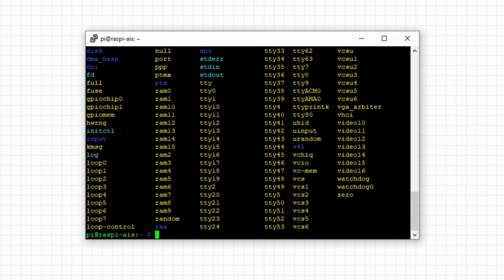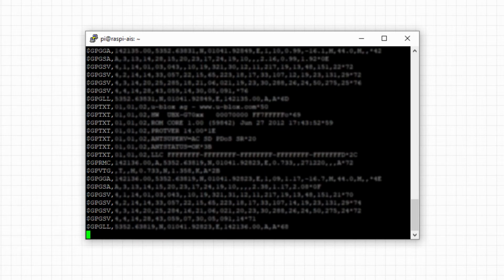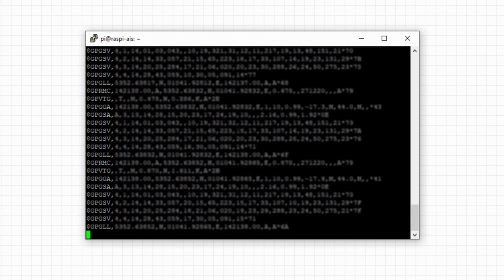which device of this folder is our USB device. So that can be found usually on the manufacturer pages and so on. So I know already that the ACM0, and we did this in the last tutorial in OpenPlotter as well, we know that this is our GPS, and we can also simply test this one by, and now don't get confused, it's a lot of data which GPSs are sending. So let's take a look there, and we will get a lot of information on this level here.